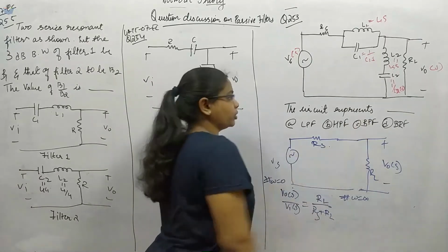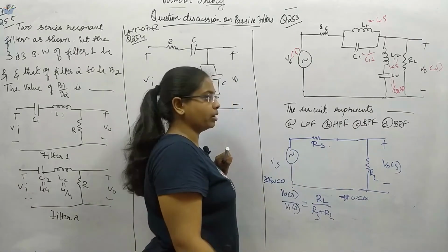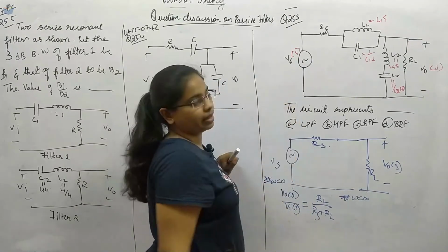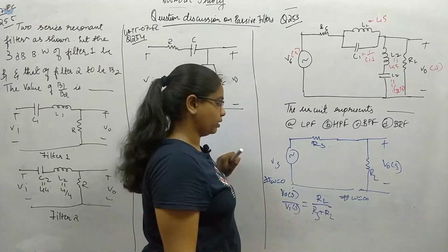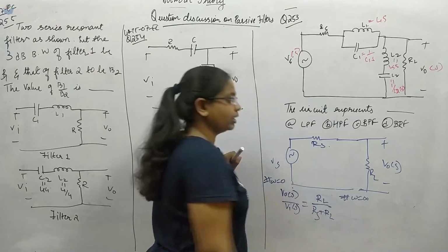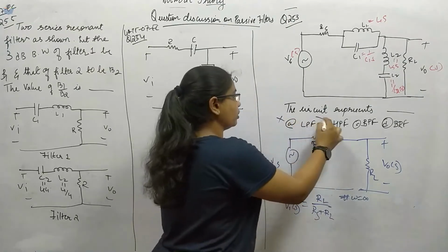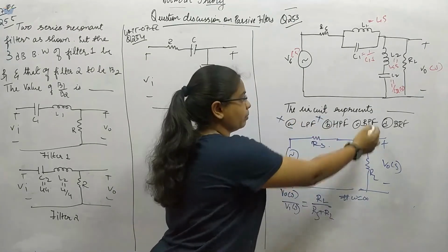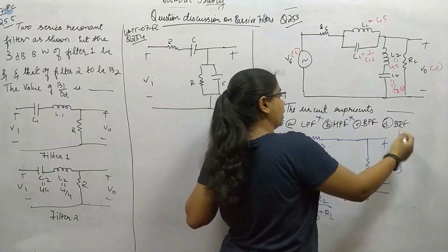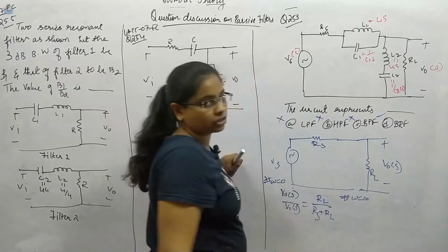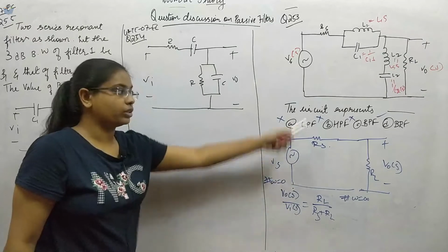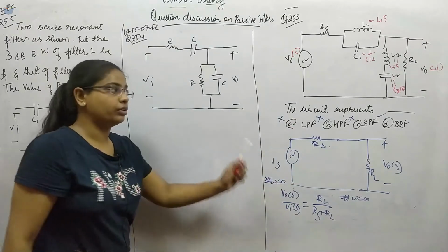Since in these options we do not have an all band pass filter, we cannot conclude directly that it is an example of the all band pass filter. Since we are getting output for both the frequencies, it cannot be low pass or high pass. For band pass filter, we have to have the outputs as 0. That is also not available. So it is band rejection filter. Solve this using the transfer function fully, then conclude whether it is an all band pass filter or not.